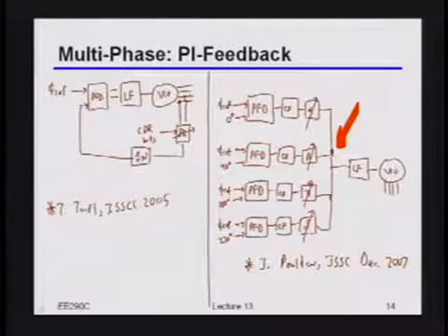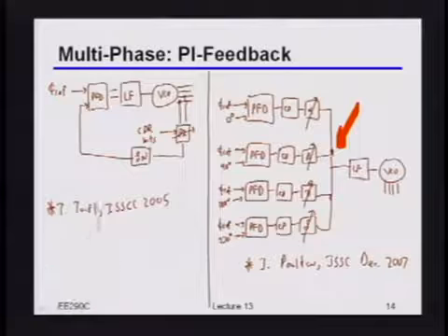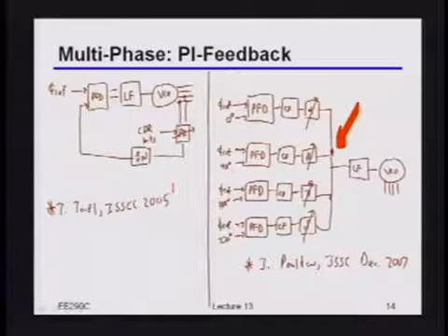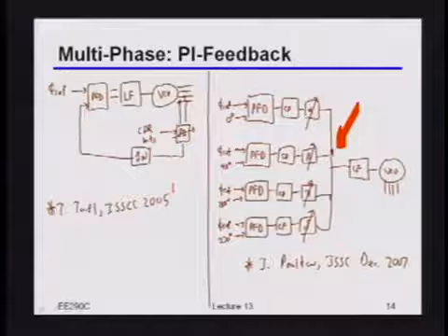Again, there are lots of different potential ways you can do these things, but some of these that we've been talking about lately, the last couple slides, are really nice when you have these heavily multiplexed kinds of systems where you really need to generate multiple clock phases all with the same controllable phase offset. Okay? Make sense to people?